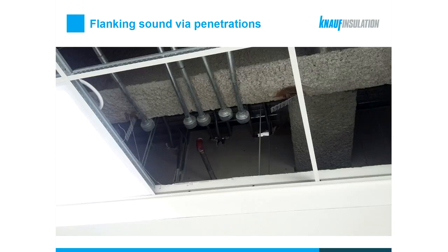A disaster. And there are no limits to the possibilities for flanking sound transmission. Flanking sound can also happen because of the penetration of surfaces. In this particular case, the architect was actually very knowledgeable, and she or he extended the partition above the ceiling level to overcome that first problem.